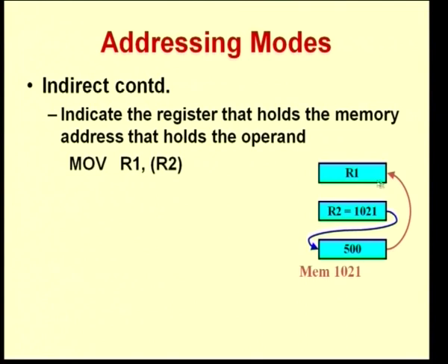In my instruction I say move R1 comma the value which AR is pointing to, 101 let us say. 101 is the address of a memory location. If you look into this memory location, you will find a value there, which is now the address of the memory location that actually holds the data. Let us say the value is 0104. That means it points to memory location 104, and this 104 has the actual value 110A, which is the data that needs to be taken out.